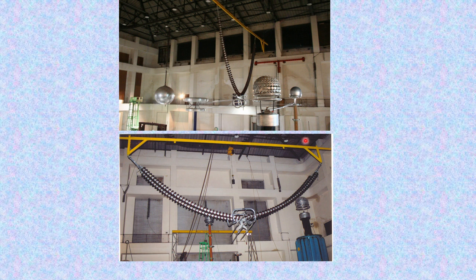This bar is like a tower, where from tower to tower the insulator strings are connected with the necessary hardware. This is again a corona control ring arrangement for the double suspension V string. With the conductors, 4 numbers here as in the field, the simulation has been done, then the voltage distribution will be measured across each disc. This is the line end, which is connected to a 1 million volt transformer here. From here we apply the voltage and see the breakdown up to the ground level, and estimation is done.